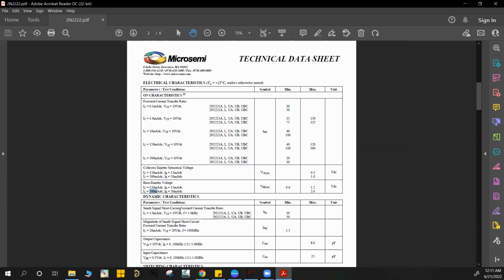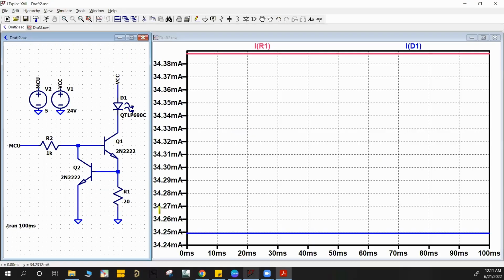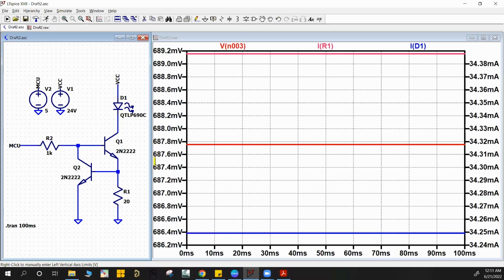But again, for this simulation, the most typical value is about 0.7 volts, and as you saw, we simulated it in LTspice, where it showed that this voltage over here, which is basically the base emitter voltage, because the emitter here in this case is grounded, right? So the base emitter voltage for Q2 was about 0.6, 0.7 volts, 680 millivolts. But yeah, so that's it for today.